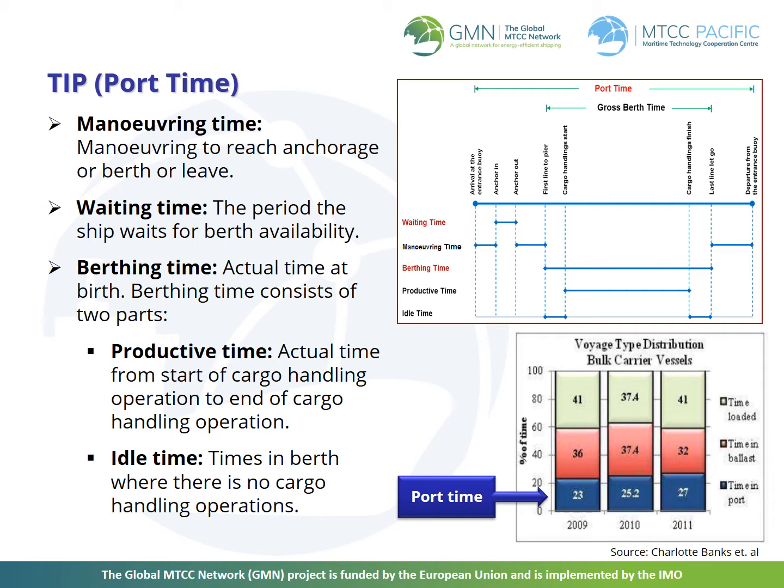According to the 2012 guidelines for the development of a ship energy efficiency management plan, good early communication with the next port of call should be an aim. This is in order to give maximum notice of berth availability and facilitate the use of optimum speed where port operational procedures support this approach. Optimized port operation could involve a change in procedures that are followed in different handling arrangements in ports. Port authorities should be encouraged to maximize efficiency and minimize delay.